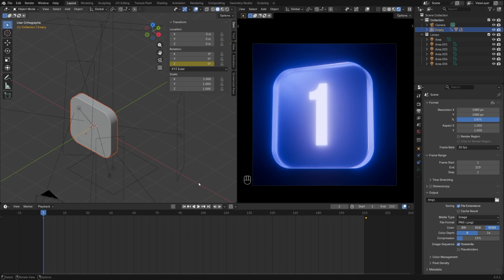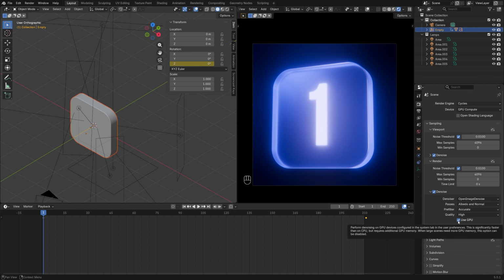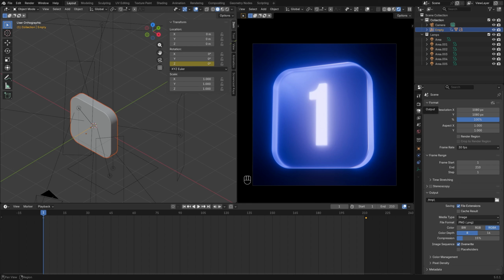The scene is now ready, and we can begin the process of final rendering. On the Render tab, within the Render menu, you need to set the number of samples and the noise reduction quality for the final render. For less powerful computers, set the max samples value down to 512, or even to 256. On the Output tab, specify the folder where the video file should be saved.